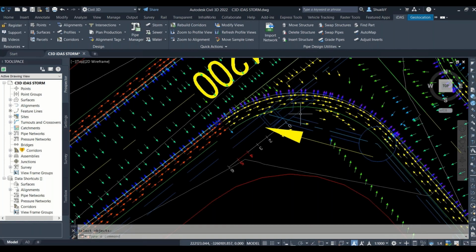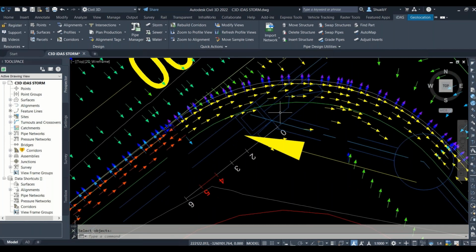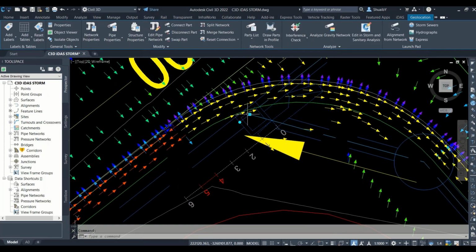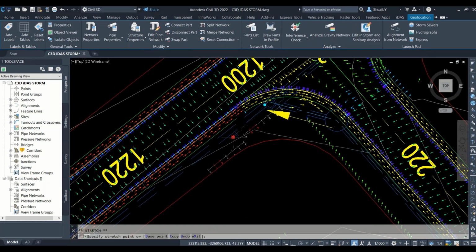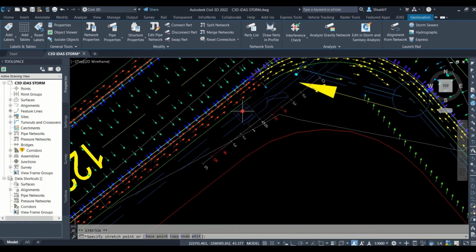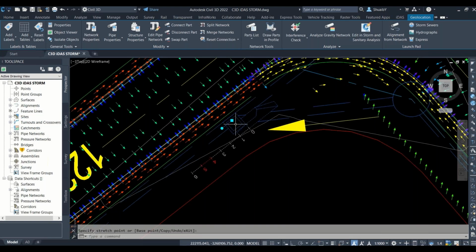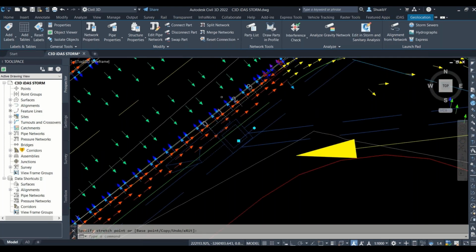Right? You might see that there is a line that's attached to it. That line is based on the guidelines of the municipality, meaning that the inlet should be positioned within that range 4 to 5, right? So that is like where the sweet spot could be from the bell mount. So that ruler actually gives you an indication of relative positioning, which is absolutely great.